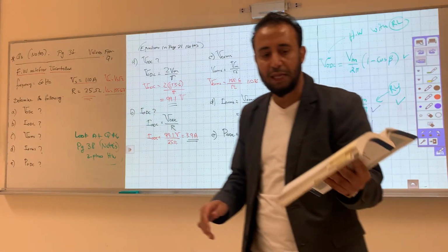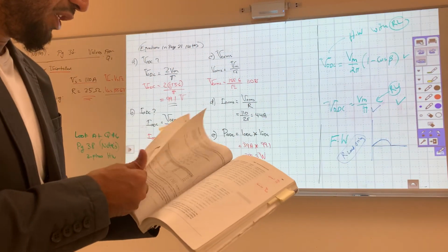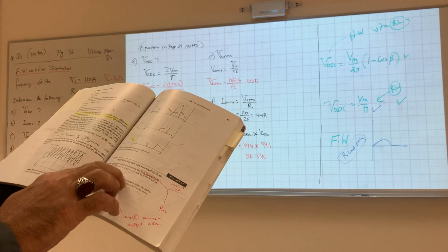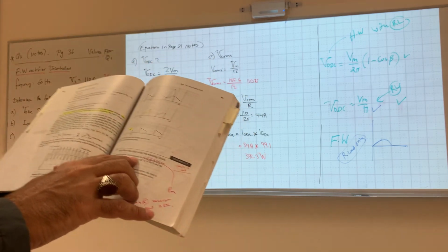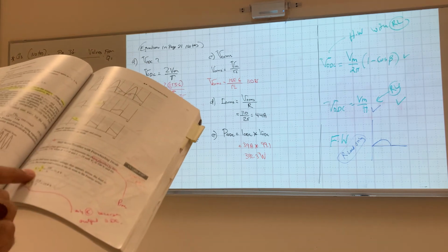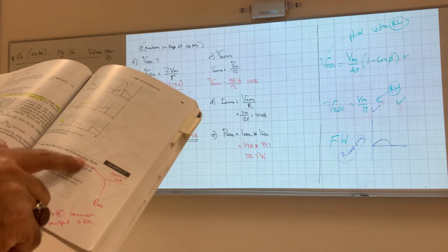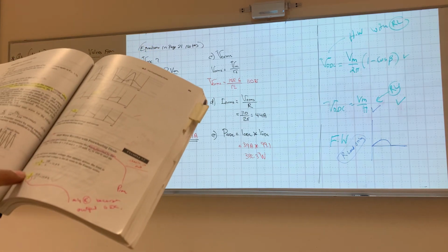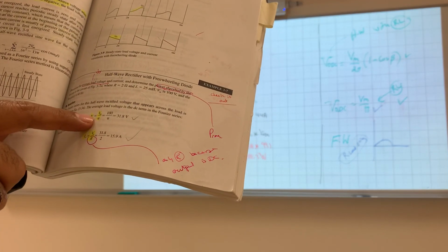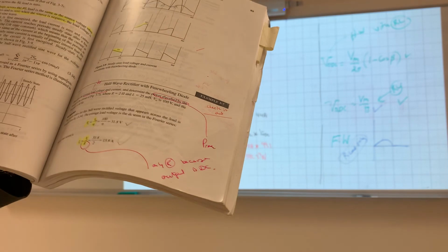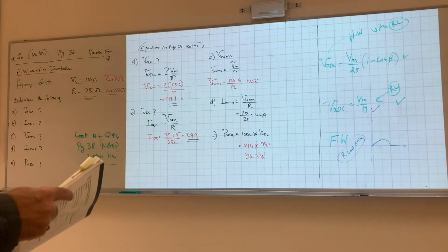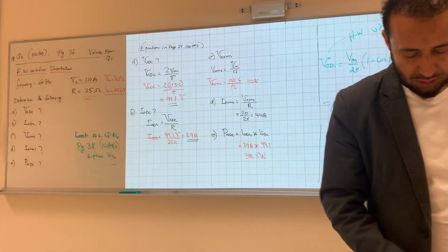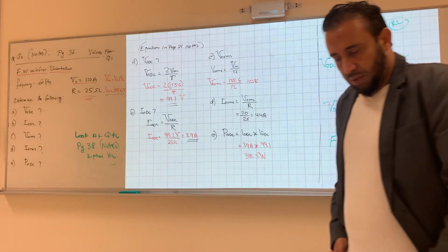It's a very good point. And you can look at this in page 83, in example 3-7. Here it says determine the average load voltage and current and determine the power absorbed by the load. See here, it's with freewheeling, half wave rectifier with freewheeling diode. But the equation that they used is V0 equals V max over pi. Okay? Just to let you know about this. I think that will be enough for today. Just some examples that will help you. Okay.